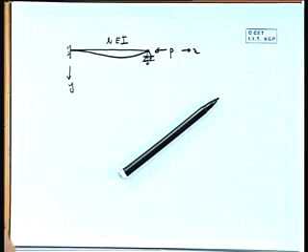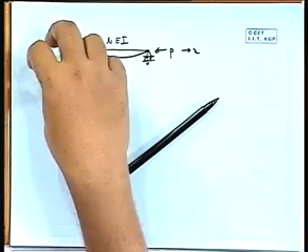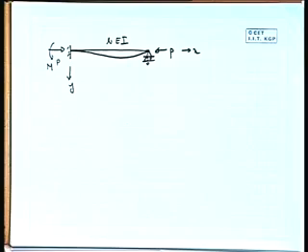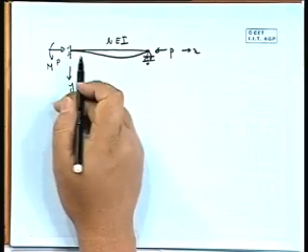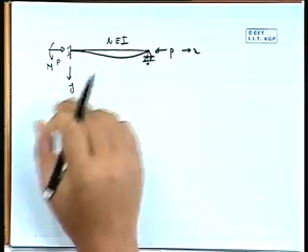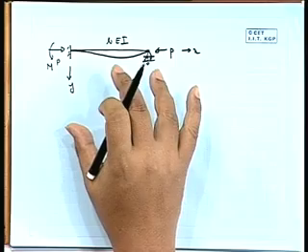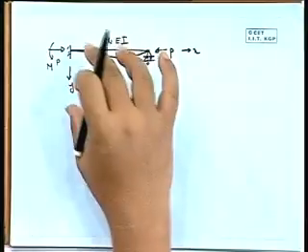the support reactions are quite complicated, because if there is a P this side, there will be a P. Now there will be a moment generated here, and at this end there will be no moment. Now this moment will be balanced by some equal and opposite force. So we can say there will be a horizontal P, there will be a moment here M, because it will not try to rotate freely, automatically some moment will be generated. And if there is a moment, say P will cancel, there is no load, only moment, that moment will be balanced by this reaction force.